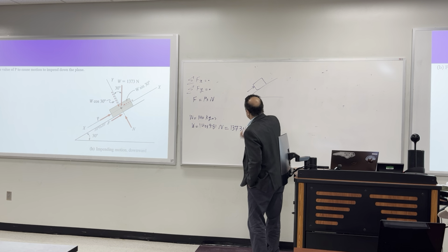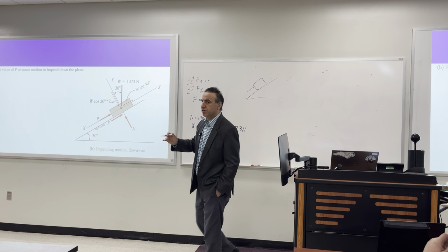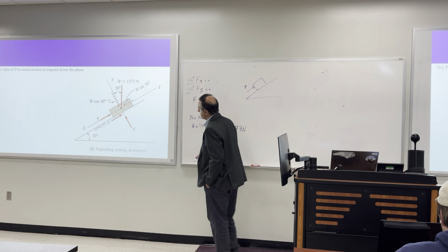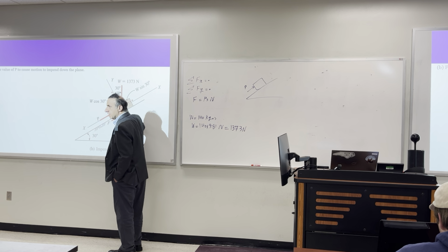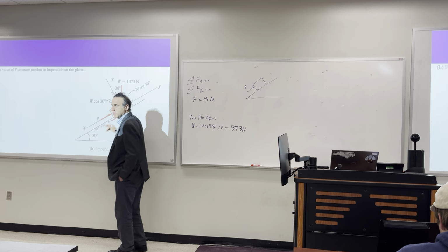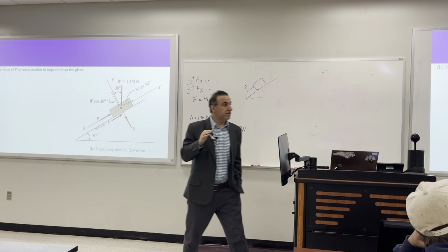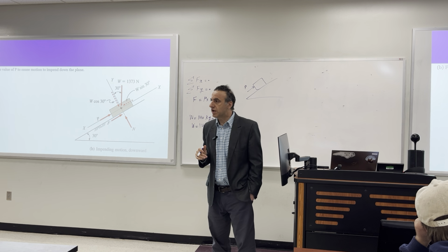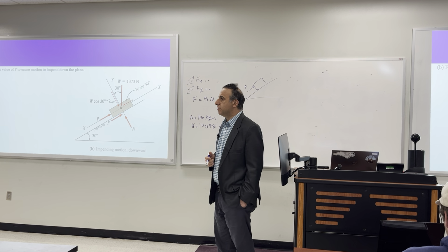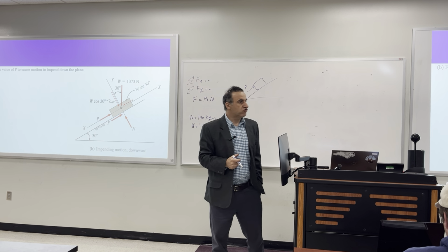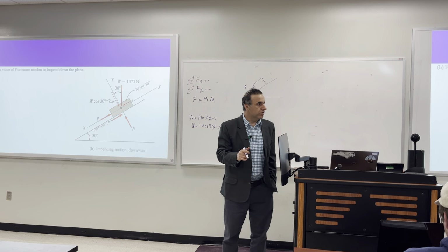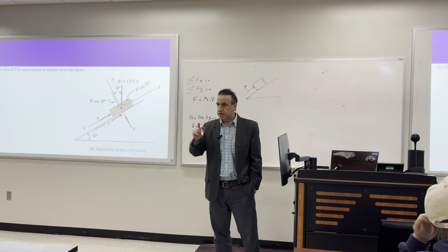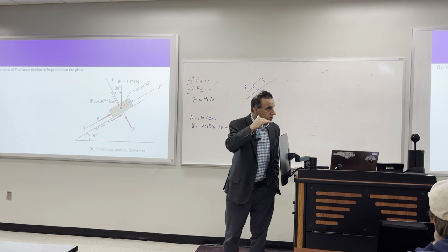You apply P, but that P is not going to be sufficient to hold your part. So if it is not enough, what's going to happen? If the P is not enough to hold it, it's going to slide down. If the part is going to slide down, then how about the friction force? The friction force is going to be going up or going down. This is very important. It's going to resist against motion.